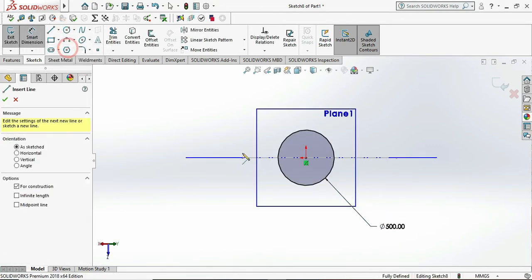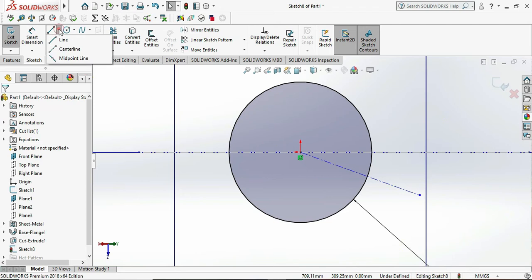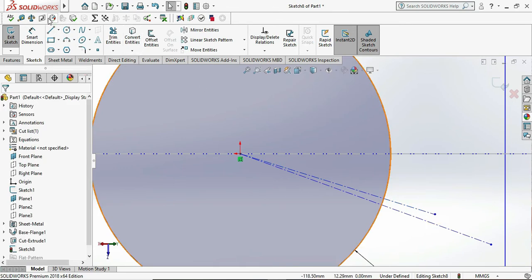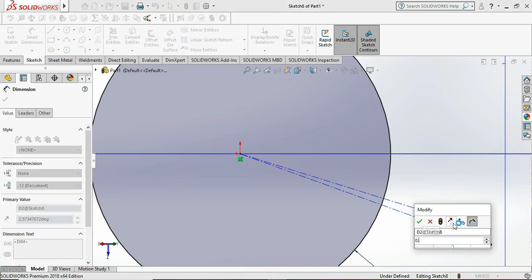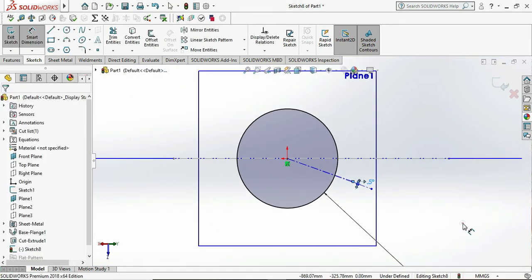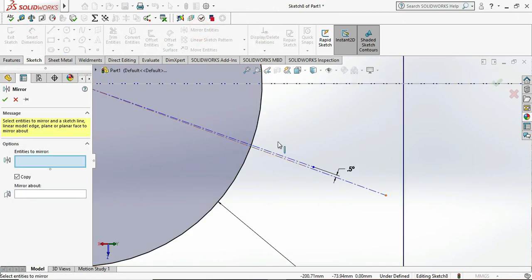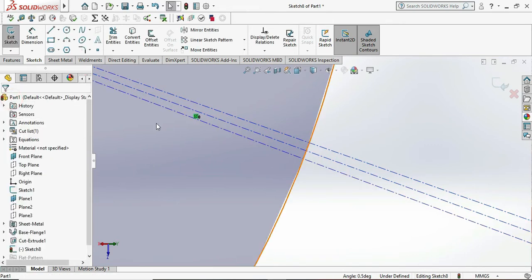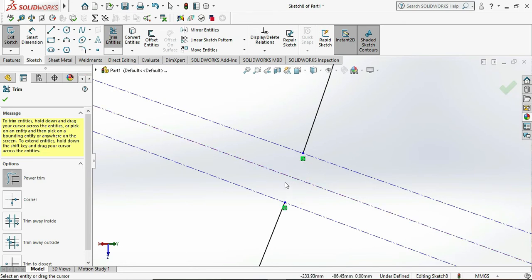Now this time the joint is in the opposite direction, so we are choosing center line here and drawing a random center line, which is not at the same position as per the left side of the duct, and taking a minimal gap. I am taking the 0.5 degree gap, which is enough to convert this shell into the sheet metal. This is very helpful. So let me trim the remaining or unwanted portion of that duct.